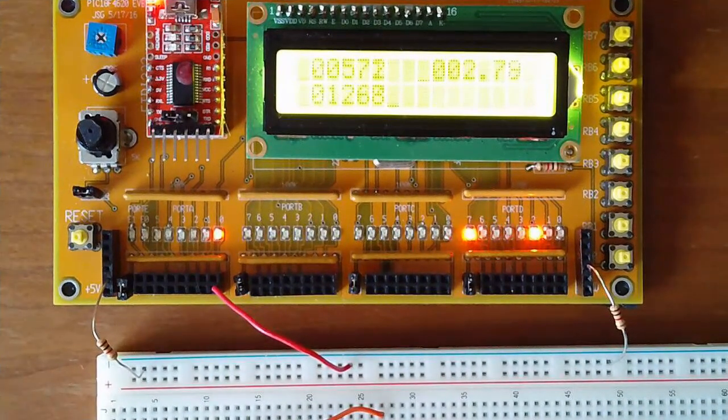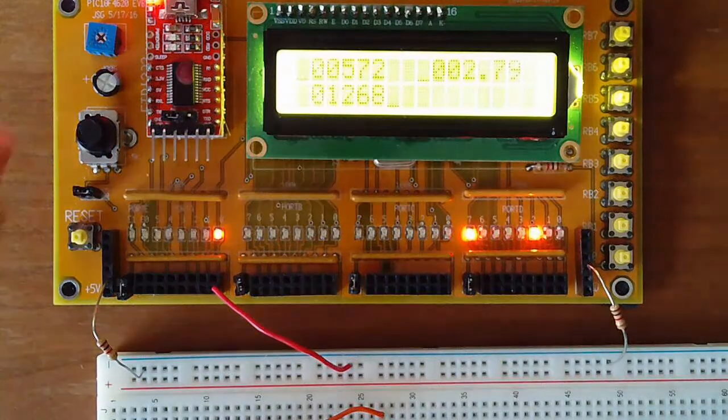And if you look at the voltages, here's the raw A2D reading, the corresponding voltage, and the resistance. Here I've got a brown, black, red, brown, black, red. This is a 1K resistor, and here's my test resistor. It's supposed to be 1,000 ohms, and the reading is off. In fact, I can change the reading with the analog input.